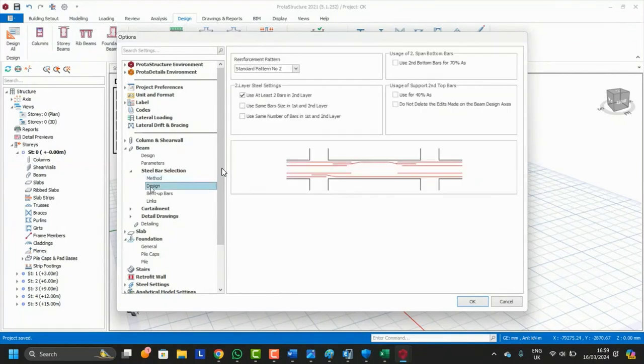You have the design. Now this curtailment is what I said. You cannot curtail your beam like this. This is so bad. So you have some options here. You have the bend up, bend down. So we will not go with that. You have type 1. This one is the poorest. Type 2, this one is now the better one. But now these beams have to, for example, this bottom red bar has to extend to this span.